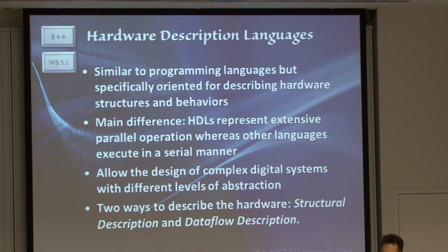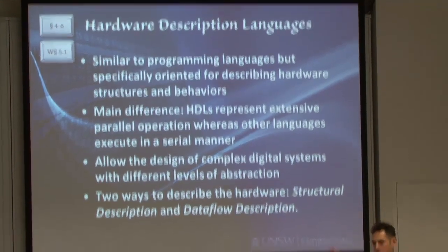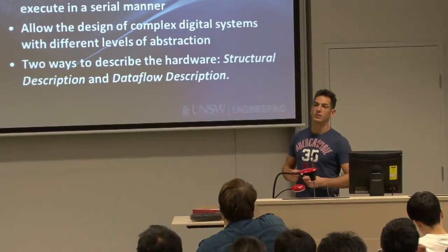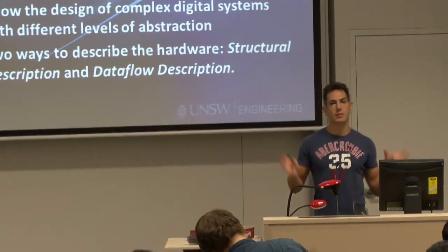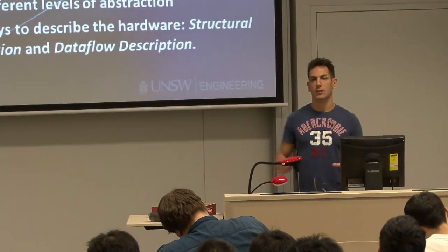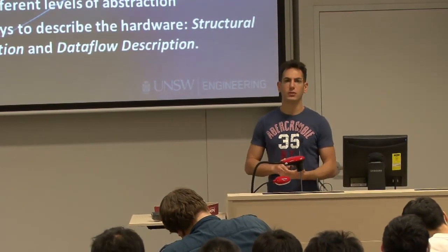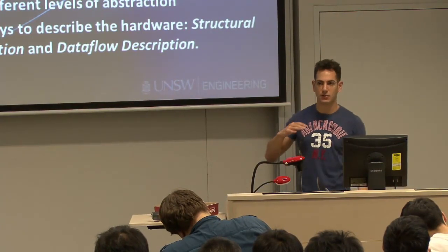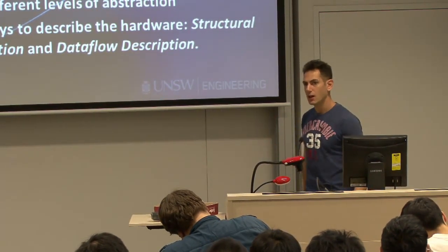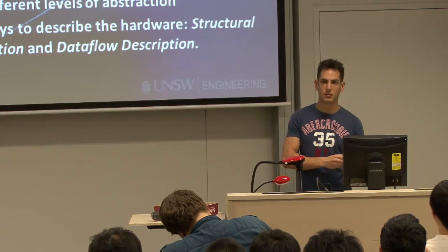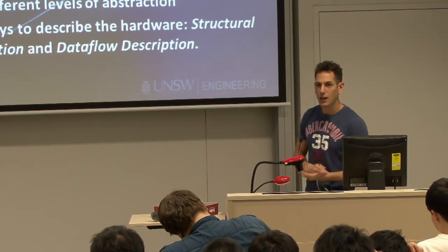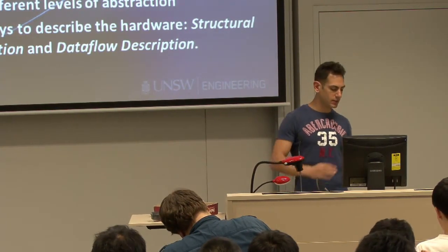And this is something that a lot of people tend to forget or not fully understand when they come to program with HDLs. This is a point I'm going to emphasize again and again: what you program in Verilog, or HDLs in general, is always parallel programming. Everything is being executed all the time at the same time. I will introduce to you some sequential commands in Verilog. We'll talk about it on Tuesday, which will look like C, and there are special structures for it in Verilog. But everything we will talk about today is all in parallel.